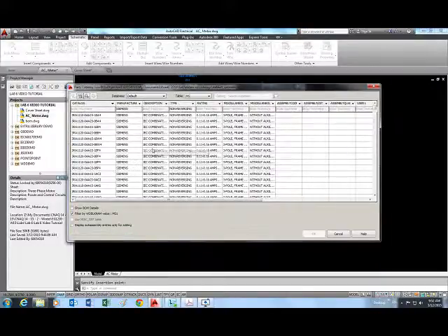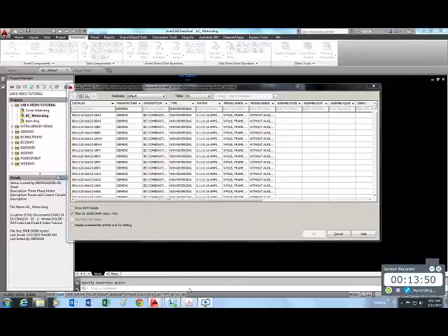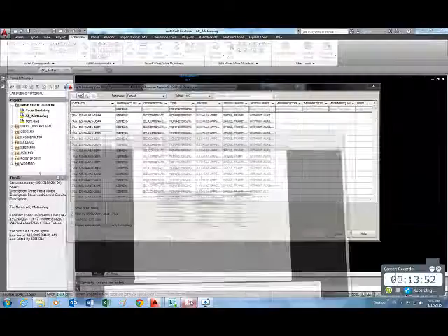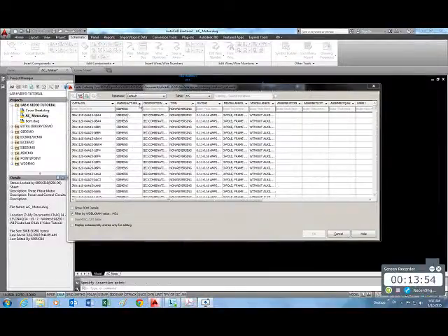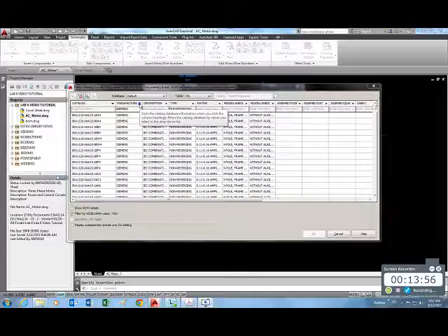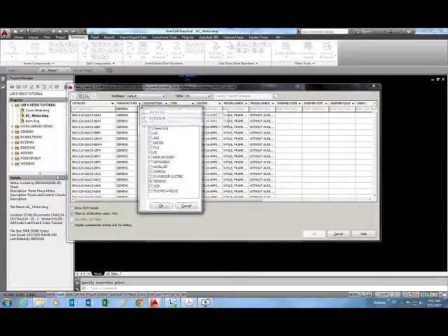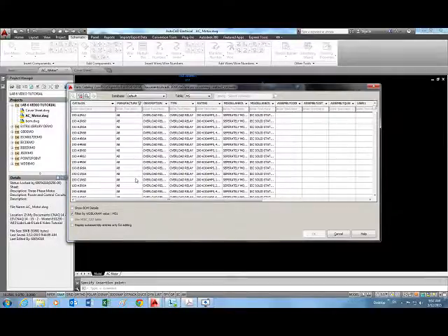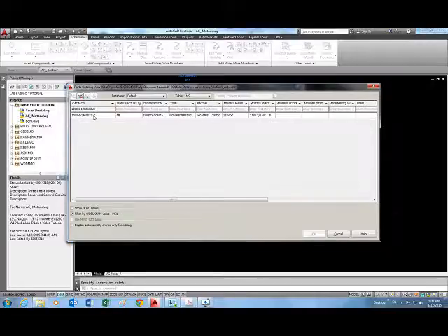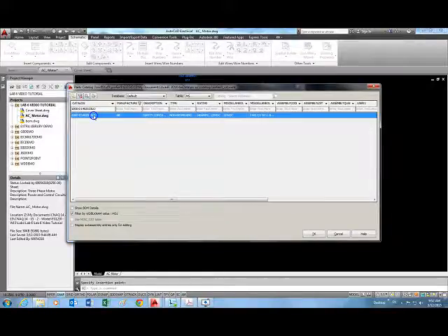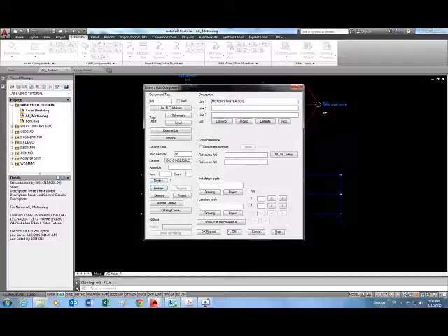Okay, here we go. And the part number actually says AB. Right now it's defaulting to Siemens. So I need to drop down the manufacturer list and click AB and uncheck Siemens. And now I can paste the model number here, or a few letters or few numbers, and that's it.